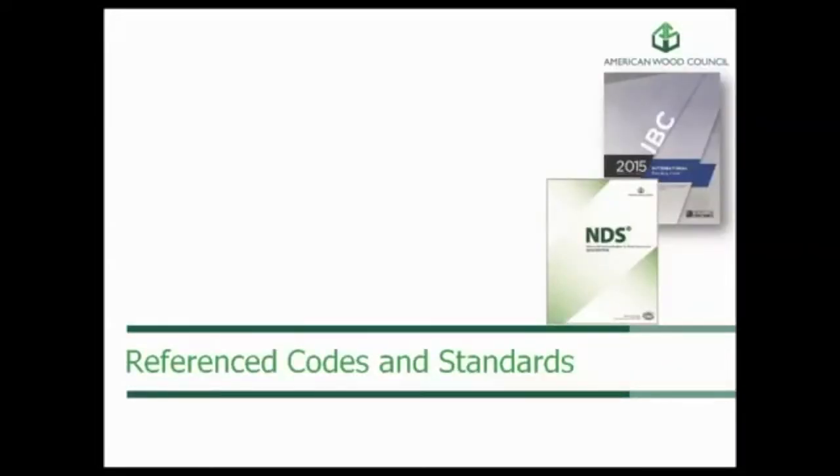I know I went through that quickly, but that's so fundamental to most of you. Once that decision is made, you never return to it typically until you change the use of the building, and then you have to go back to that again. Always consult your code official if there's any question from the very start about the use of the building. If you're, of course, a consulting engineer or an architect, you could save yourself a world of trouble by coordinating with the code official at the very start on that, naming your use groups.